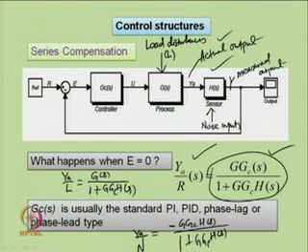Now, why are we finding all these transfer functions? To see the effect of different types of inputs on the process output. The process output is made up of 3 outputs: one given by the reference input, the load disturbance input and the noise input. Now, how is the controller designed to have a perfect tracking system from this series compensation scheme?